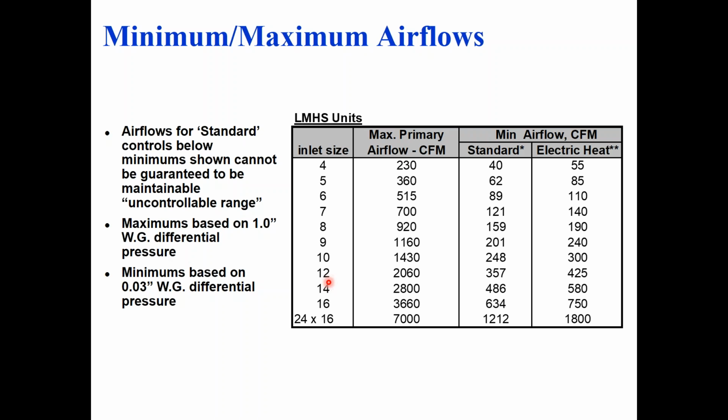If you specify anything other than 6, 8, 10, and 12, you should question yourself. For example, if you need a size 4, why do you have a zone that small? What's going on? It's not impossible. You might need it, but you should be questioning yourself. The size 5 box is dumb because a size 5 box is actually a size 4 box with a reducing collar on the inlet shipped to you that way. It is literally that.